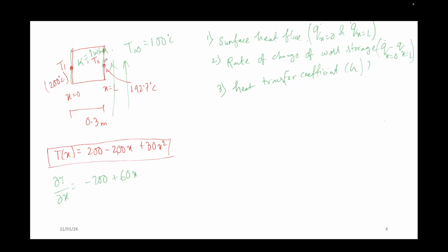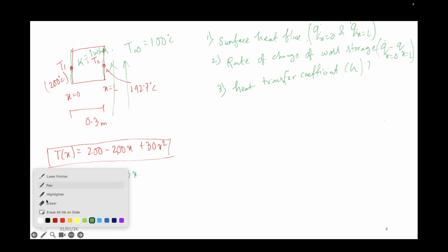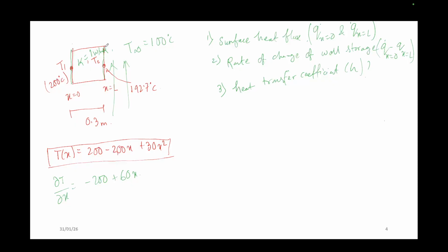If I talk about this surface, let me show you with another color. So this black color surface you observe is your solid surface. This solid surface has Ts. As there is a temperature, a heat flux is there, right? This heat flux here is because of conduction, and because air is flowing outside, the temperature will reduce because of convection. So that's why this is your convection. So this is your mixed boundary condition.